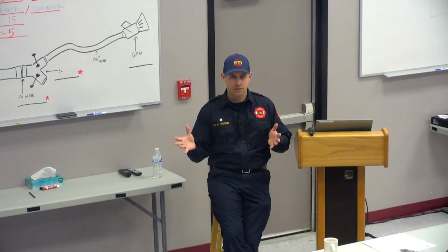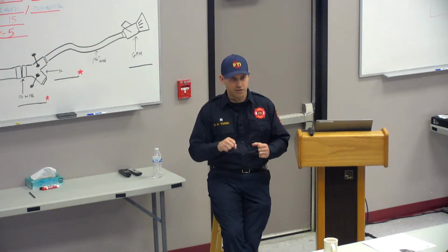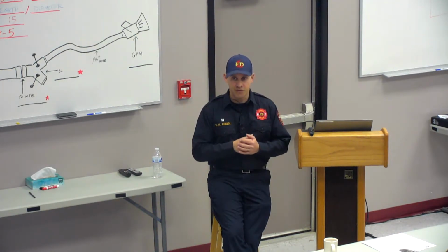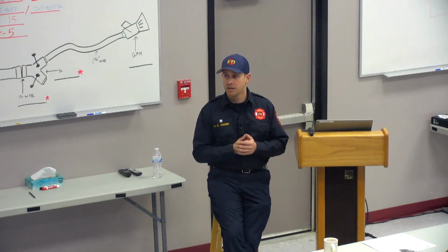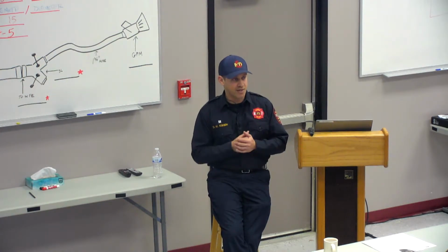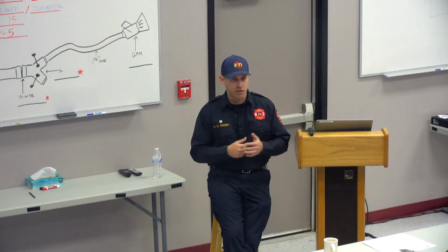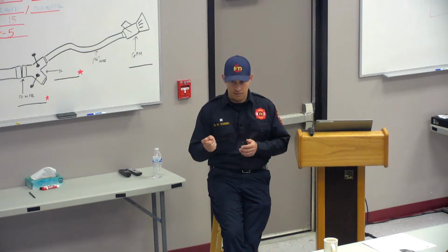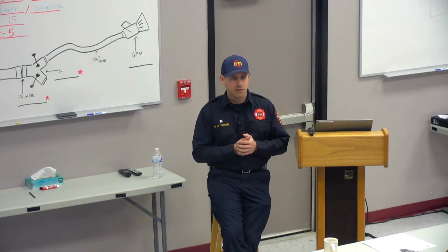Supply line. Is it hard? Do I step on it and it feels stiff? Okay. If it does, I've got water moving through it. Where's my next step? Somebody. Intake open? Is the intake open? Seen that happen a lot, right? It's an easy step to miss, especially if you've dropped the tank already and already given them water on one of the hand lines. That's the next step. All right, that's open. What are we looking at now? Make sure the water's actually coming in. Yeah. Do we need a prime?